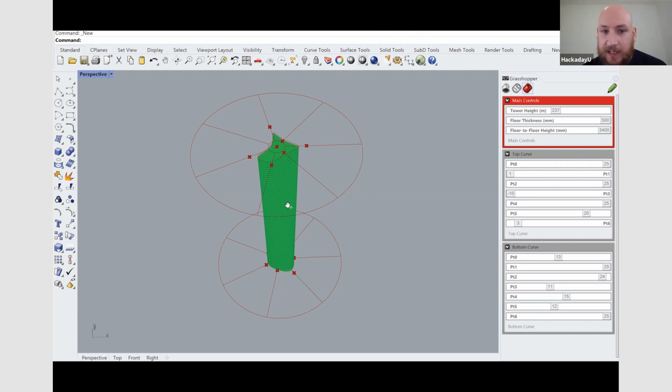What I've done here is create a circle on the bottom, and another circle; you can't see that circle there. So two circles, divided them, I think 7 times, and created a line between each of the 7 divisions on both circles. Then you can move a slider to move each of these points along each of these lines. A NURBS curve gets drawn through these 7 points.